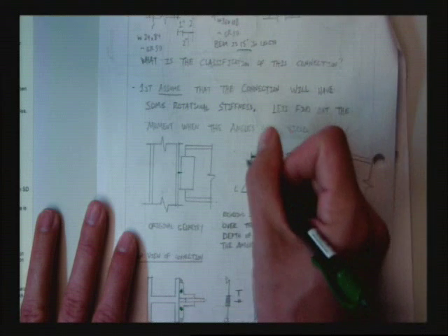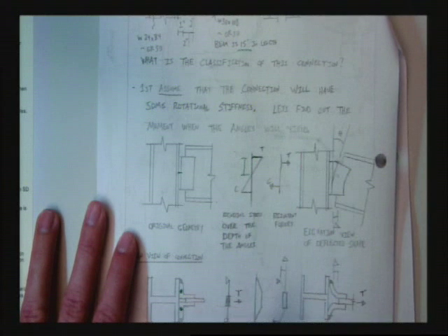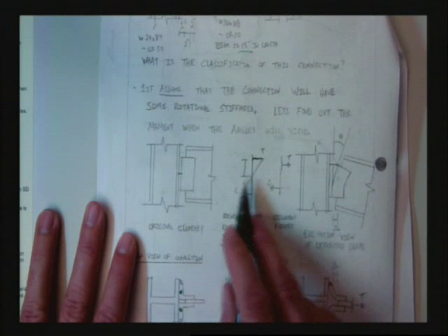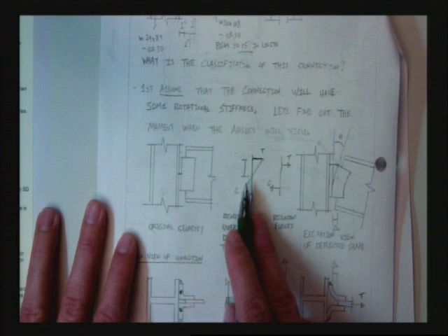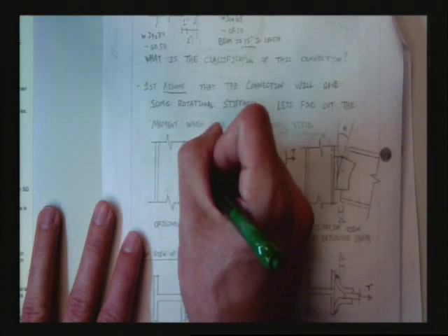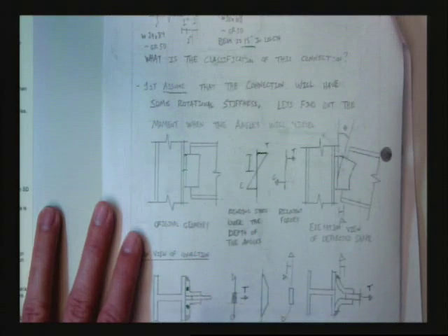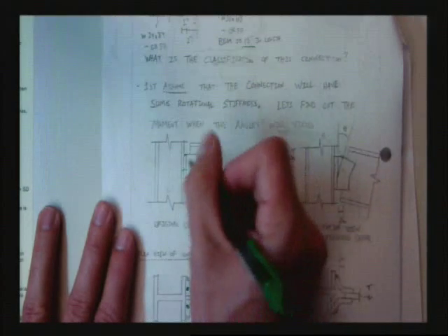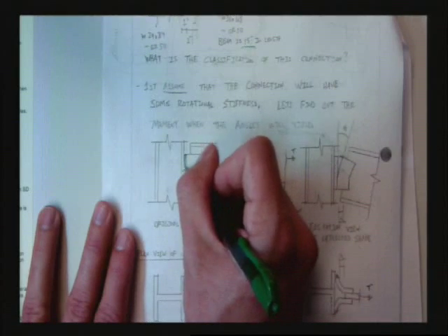How about the whole thing? We're going to allow the whole thing to yield? Probably not. So how much? Just enough to make it. This is the part where in the class there's no right answer. What I'm trying to get at here is that if I only allow the top fiber to yield, then as soon as that yields right there, we'd have to stop. If I'm going to allow the whole cross section to yield, I'm going to allow all of that to yield when I stop.